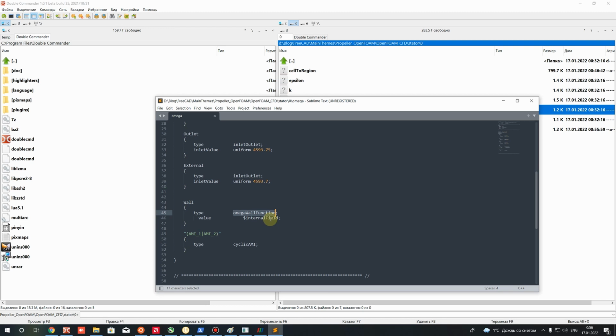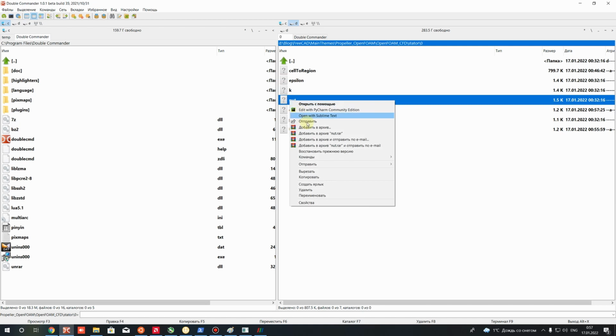Here we have a smooth surface, but we can use the wall function, just the omega wall function. If we have y plus for a tetrahedral mesh, for example, without boundary layers, with a very rough mesh on the surfaces, we have to use the wall function to get the right velocity profile. Okay, let's use this omega wall function here. Let's close it and let's go to nut.